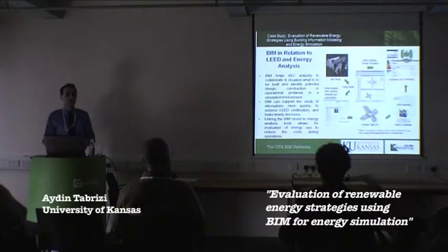With the development of the virtual environment tab, we can now synchronize LEED Online and the virtual environment tab. In real time, you can see how many points you can get based on the LEED criteria, and you also have real-time access to your own project when you have any change in the energy segment or any other sector. And of course, linking the BIM to an energy analysis tool allows for the evaluation of energy use during the operation phase.